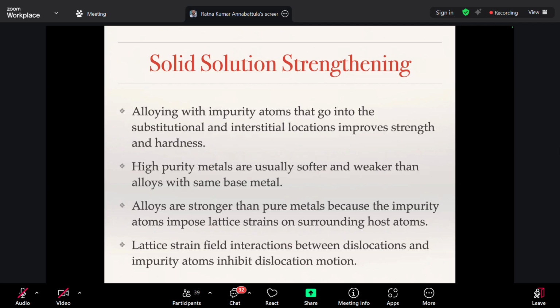That is what we call strengthening. The material is becoming stronger after yielding because the dislocations are interacting with the grain boundaries. The grain boundaries offer resistance, and as a result the strength of the material increases. Got it?